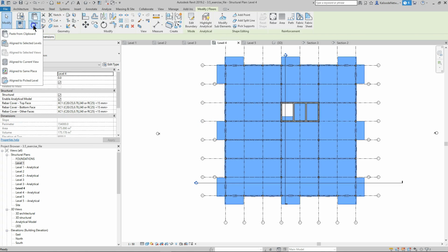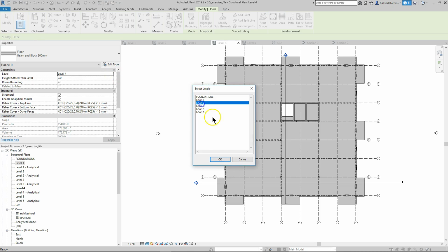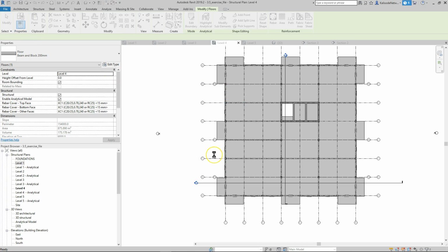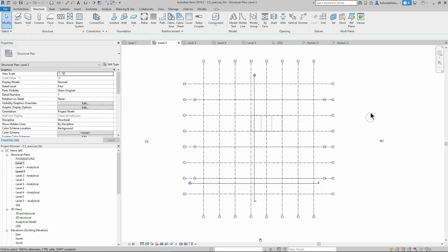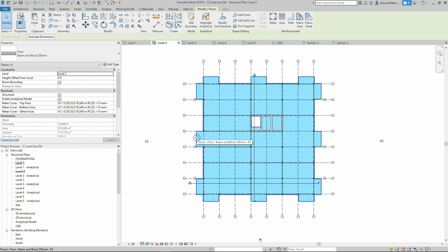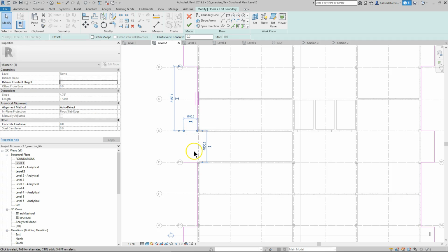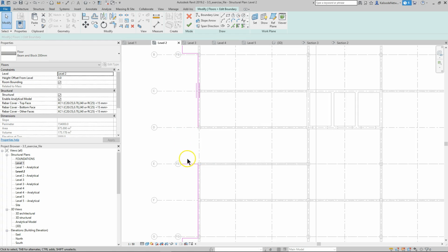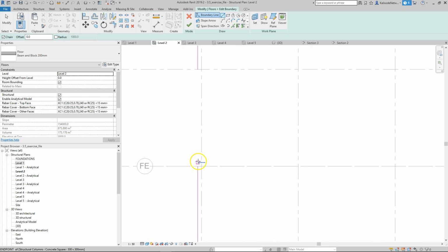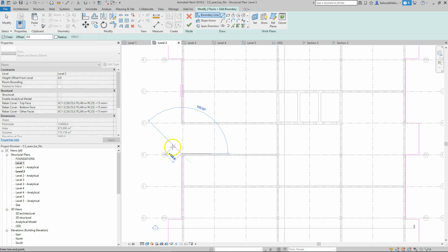Now I want another version here at floor 2, because there is a main hall, a hall entrance, and in here you can see it. This is my model. I will click on it again, and I will edit boundary. Now I'm selecting this lateral line, and now this lateral too, and I will draw more lines here from the corner.